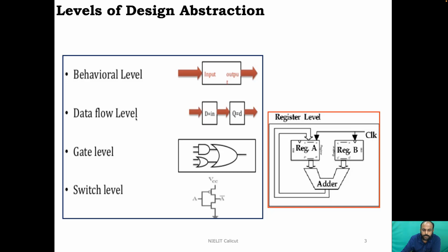And also, we call the code written for synthesis RTL code, wherein RTL stands for register transfer level, wherein the code is described in such a way that it shows how data flows between different registers. So this particular way of writing the Verilog descriptions that can be synthesized is called register transfer level.